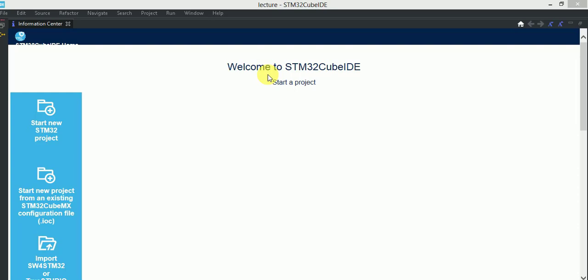To perform this experiment you have to use a controller that may or may not have an RTC, because most of the controllers these days have the RTC engine embedded inside the chip. But there are some kinds of controllers that do not have such functionality, so we have to use a different RTC module for that.